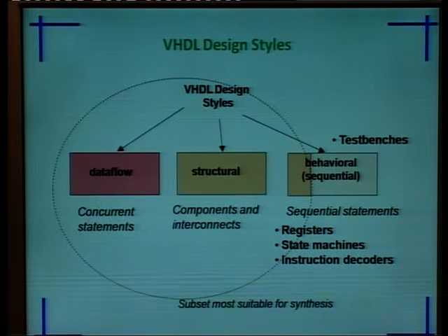Now next is the VHDL design styles. In VHDL, there are basically three types of modeling. Whatever combinational circuit we have, we can design it in three different ways. We can design our adder with the data flow type, the structural type, or the behavioral type. In the data flow, we write the Boolean expressions and directly deal with the flow of data from one side to the other.